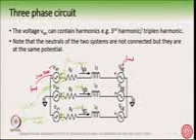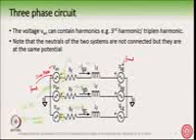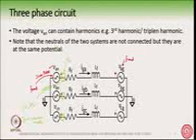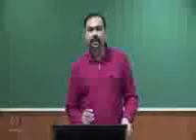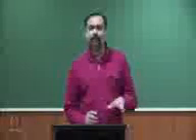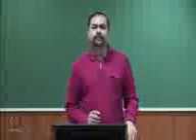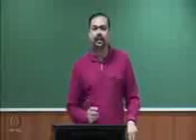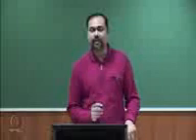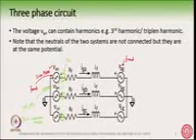So this current cannot flow. There will exist a common mode voltage in all the three phases, but there cannot be any current flowing. IgA, IgB and IgC cannot have the third harmonic, ninth harmonic or 15th harmonic. Those currents cannot flow.